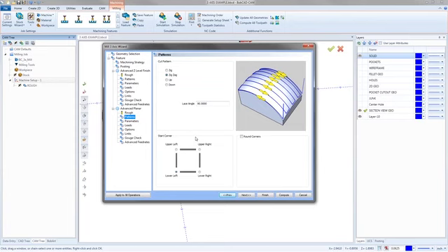And really, the way I think of it at least, this is the cleanup crew toolpath. It's the one that's going to come in and clean up a lot of the things that the other toolpaths might miss. This one should always be in your arsenal somewhere. Now, it's not the fastest toolpath to run, but it does a really good job when, for whatever reason, you need it. It can cut steep walls. It can cut flat floors. It can do any angles, really. The only time this toolpath has a problem is when it's got to cut along the same direction that it's moving in.